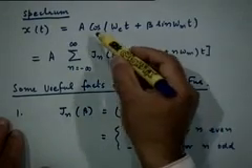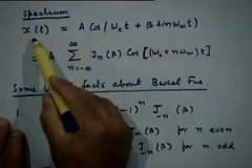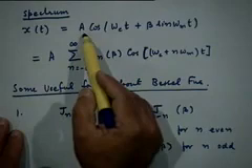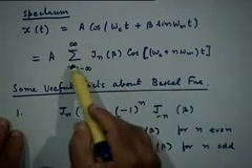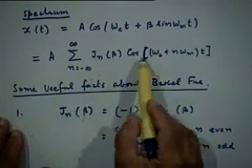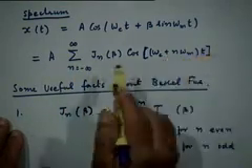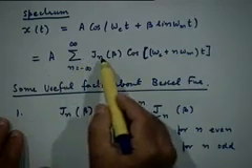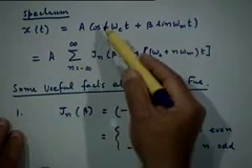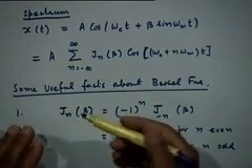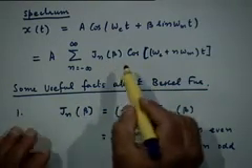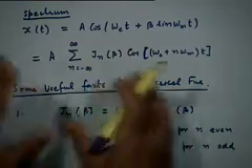Look at these two expressions. If you look at the power in the signal, what is the power here? A square by 2. What is the power in the signal here? Every sinusoid that you have in the signal has a power A square into J n square beta by 2, and obviously they represent the same signal, so the total power must be the same, right. So it's obvious that this kind of property must be satisfied, irrespective of the FM case, of course, under which we are carrying out this discussion.